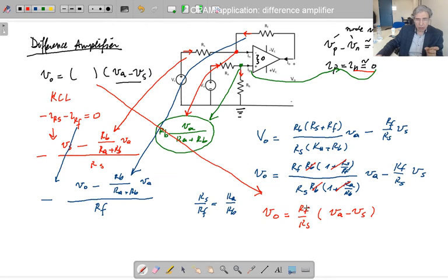So you've got to increase that in order to make it measurable in an electrical sense, I mean. So you are going to measure this voltage. Once you measure that voltage, that means you found this difference, and according to the sensor properties, you can transfer this voltage back to the original physical quantity that you are trying to measure. Therefore, we use difference amplifiers quite often in practice. So this is a good application of an operational amplifier. So that is the end of this video.